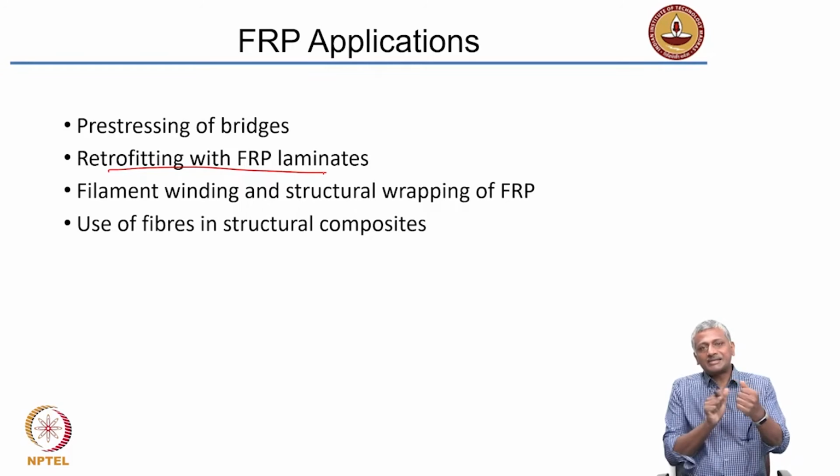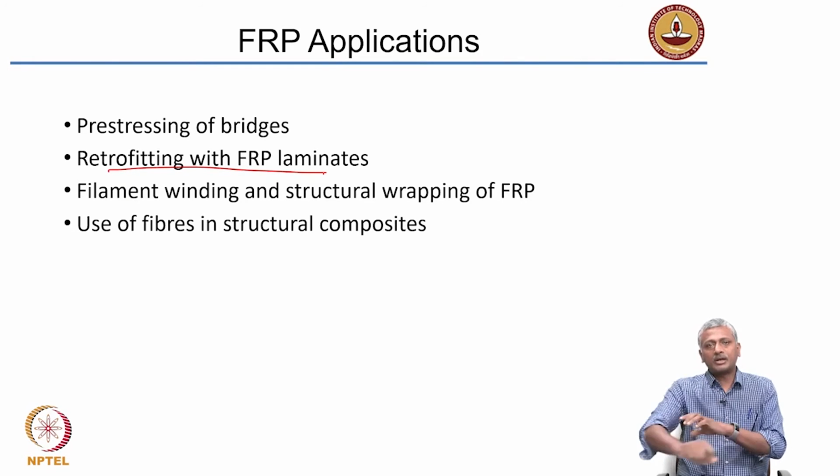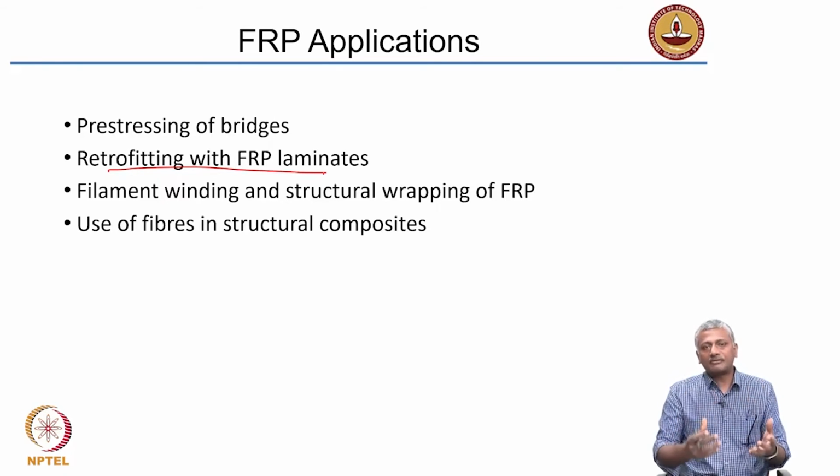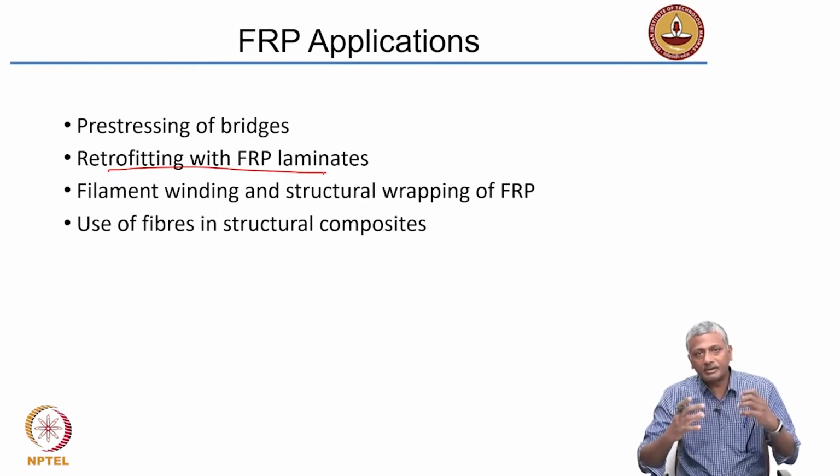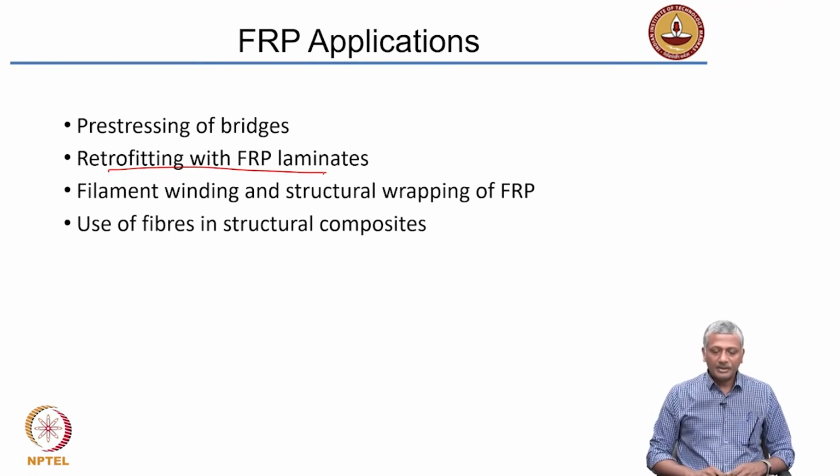What they do is they take these laminates and wrap them around the concrete. Supposing you get a fracture, what do they do? They wrap it with a plaster. Plaster ensures that your hand becomes very stiff. You can't move your hand or that joint which has got fractured until it heals. In the case of concrete, if there is a lot of cracking, you put this wrapping around it, so what it will do is it will strengthen the concrete within the wrapping area. Okay?